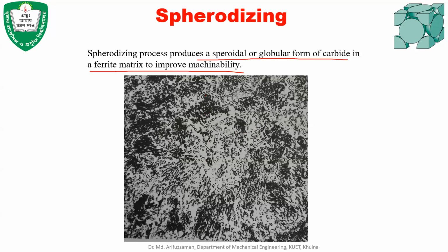That means the pearlite, the carbide, that means iron carbide or cementite particles or cementite grains, can be modified to become circular or spherical, okay, to improve the machinability. Cementite is a very hard material, so if we can produce circular cementite, then we don't need to cut it. For example, you have a cementite like this, and you have a cementite like a circle, like this, and there's another cementite in here, and there is another cementite in here.